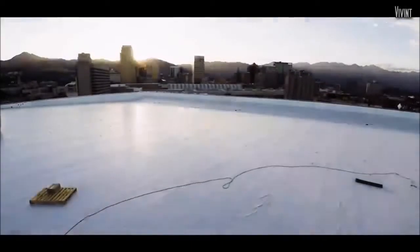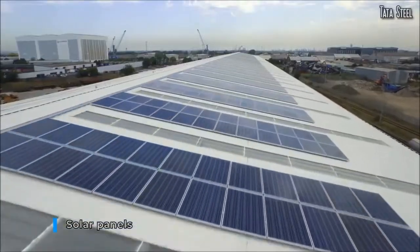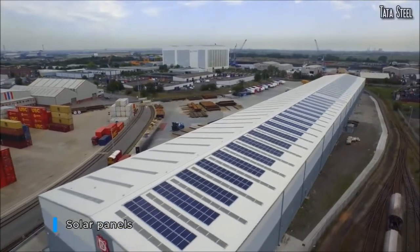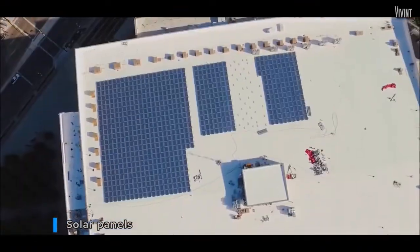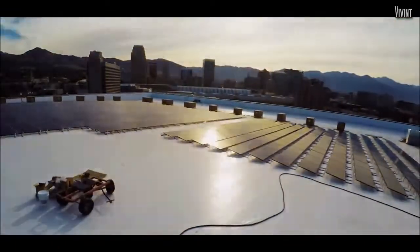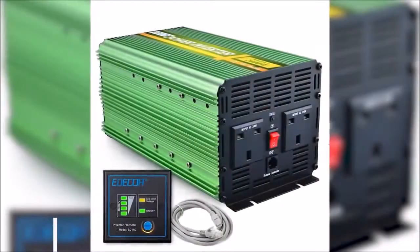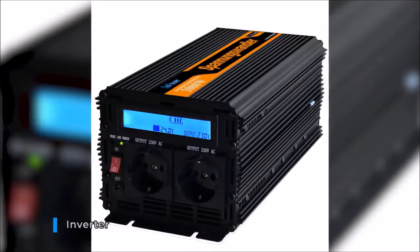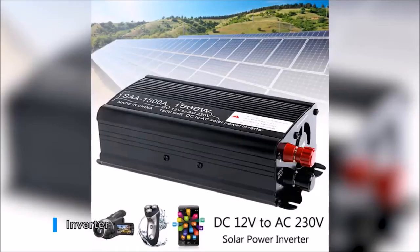As I explained before, the solar panels generate electricity when they are exposed to light. More specifically, they generate DC electrical current. But in order to use the electricity produced by the solar panel, you have to have AC electrical current, which is the type of current used by your home and the power grid, so you need an inverter. An inverter converts the DC electricity generated by the solar panels into alternating current. The solar panels are connected to the inverter not one by one, but in groups that are called strings.